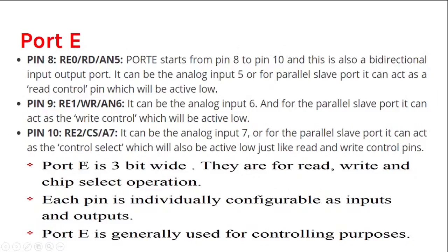The next is port E. Pins 8, 9 and 10 are port E. Port E has only 3 bits, only 3 pins. They can be used for multiplexed functions: read, write, and chip select for the parallel slave port. So it's a 3-bit wide port E.